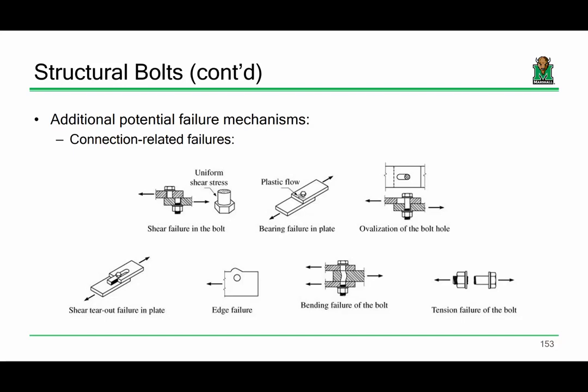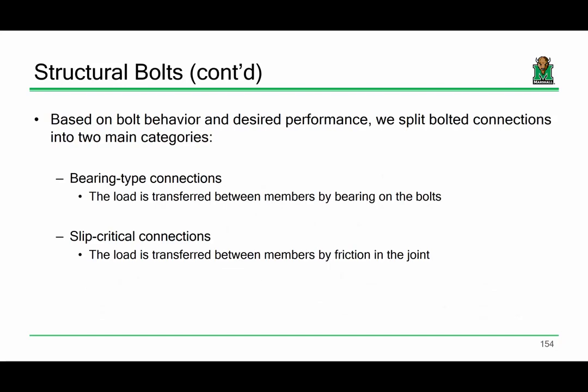Yes? What's that? Which one? We did, yes. That's a great point. This is the limit state we were assessing when we did threaded rods. So we were assessing it in tension. And not only that, but when we reduced the area by 0.75, we were assuming that the failure would occur at the threads and not through the shank, if you will. That's an excellent point. In fact, the equation was exactly the same. So, sound good? All right.